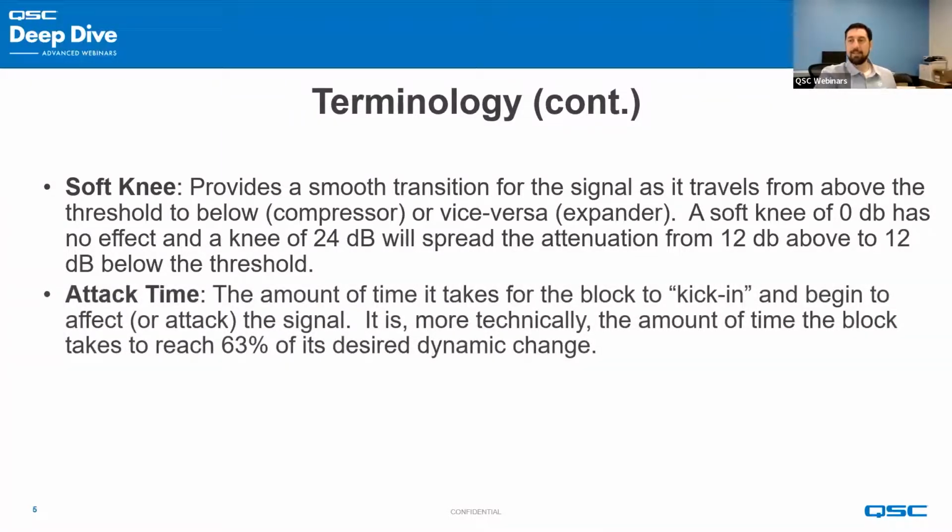Attack time. This is the amount of time that it takes for the block to kick in and begin working. If you want to get super technical when you're setting your attack times, it is technically the amount of time that the block takes to reach 63% of its desired dynamic range. So almost 2/3 of the way to where you want it to get. That is the time that is referenced in attack time.